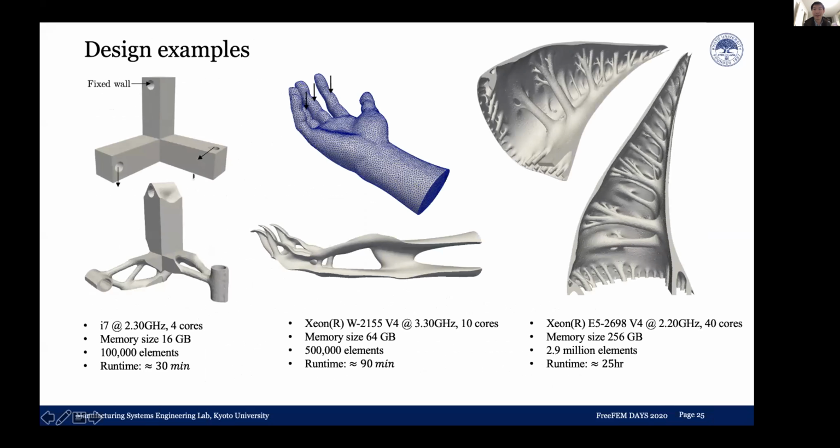Here, we wanted to give you an idea about the solver's parallel efficiency. So we solved 3 different sizes of problem. The smallest problem has a 100,000 tetrahedral mesh, and it is performed on a MacBook Pro. And the total runtime to convergence is around half an hour.